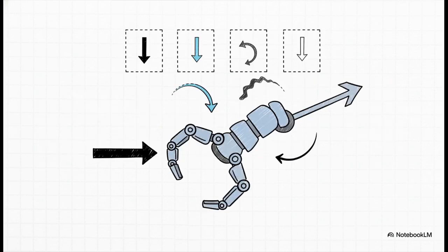So the crucial trick here is just methodically dropping the raw numbers into their slots. You have the base acceleration on the left. The middle term handles the centripetal acceleration of the whole system spinning. Then there's that fascinating term with the 2 in it. That's the Coriolis acceleration. It's kind of a phantom force created by moving linearly inside a spinning frame. We add 2 times the base rotation crossed with the relative arm velocity, and finally we cap it off with the relative acceleration on the far right.